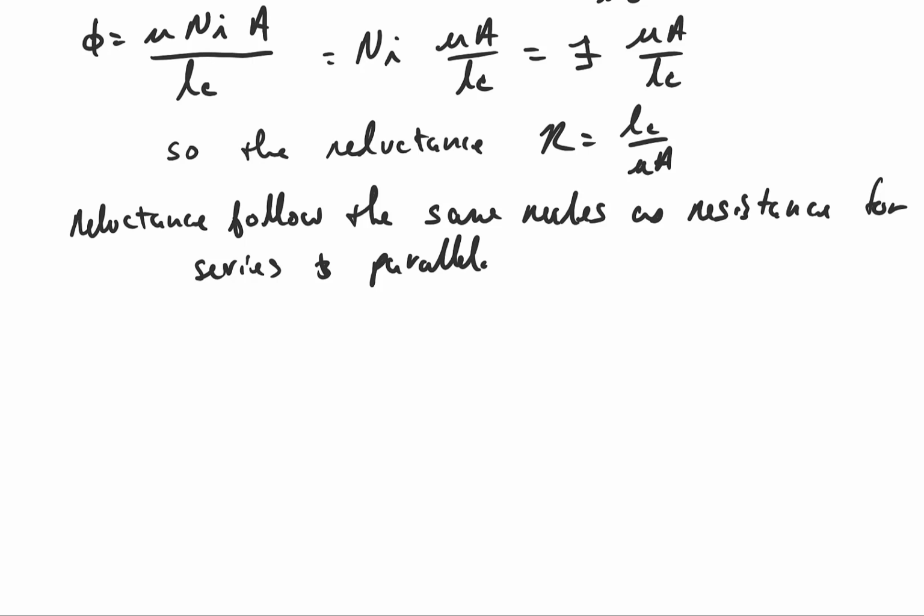And if we use these ideas, the simplifications that we're making here, to take something that would be solved by Ampere's law using a path integral and solve it algebraically, we're going to get to within about 5% of the true value. And that 5% error comes from a couple different places. One, we are assuming that the flux created by the current carrying coil of wire is all confined within the magnetic core, where in reality there is leakage flux outside the core.